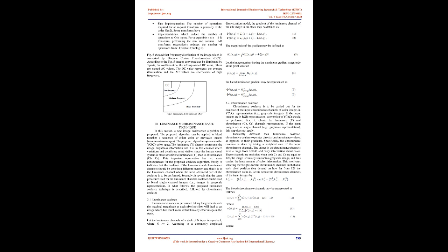Owing to the large statistical variations among data, the optimum transform usually depends on the data, and finding the basis functions of such a transform is a computationally intensive task. This is particularly a problem if the data blocks are highly non-stationary, which necessitates the use of more than one set of basis functions to achieve high decorrelation. Therefore, it is desirable to trade optimum performance for a transform whose basis functions are data-independent.